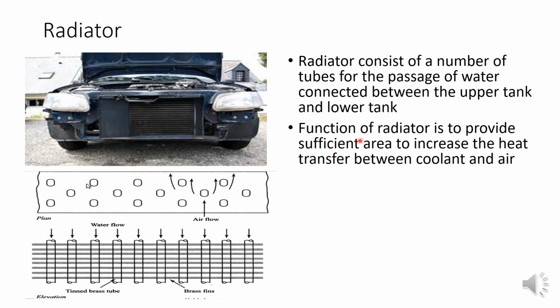And the function of the radiator is to provide sufficient area to increase the heat transfer between coolant and air. So why do we require a radiator? We can simply pass hot water through a single pipe and pass air, but in that case heat transfer will not be much. Here the heat transfer is by convection.